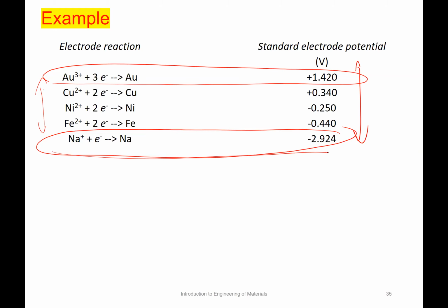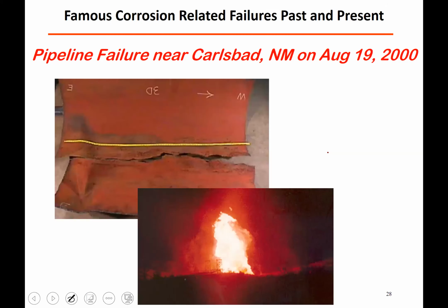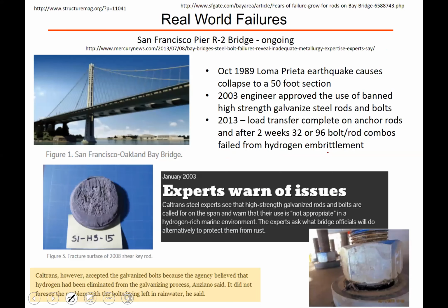And so this is particularly useful when you're really in the field and designing, right? If you have something like steel versus zinc, you look up the galvanic series, and you would go back and look at your table to do your design.